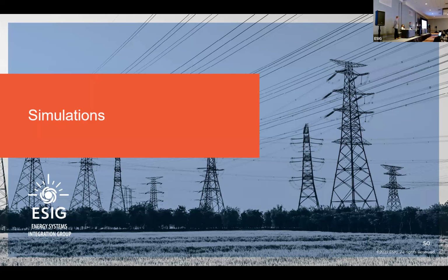Yeah, no, and it is happening in the 2800 circle as well, right? There's a huge range of operating conditions which an IBR can face in the system. The short circuit ratio can go from 5 to maybe 40 or something. So it's a big range, and you can have large ranges of impedance spectrums. During the initial design evaluation, something like what is proposed in 2800, it's never going to be able to fully encompass all of the possible grid operations. So there's always going to be surprises.